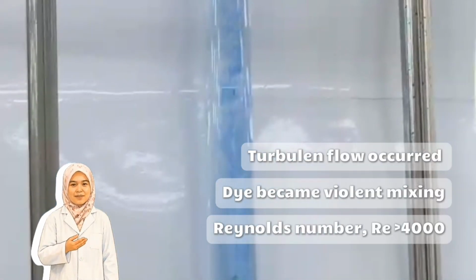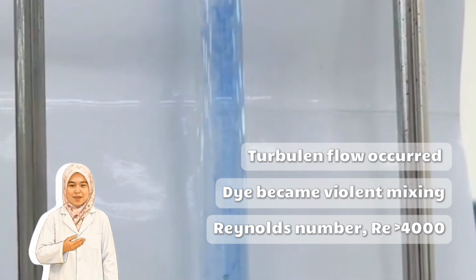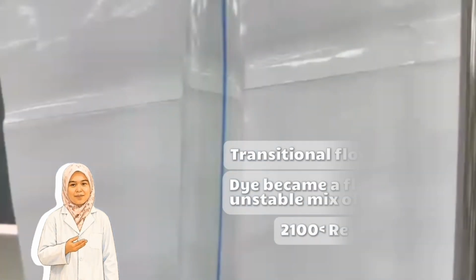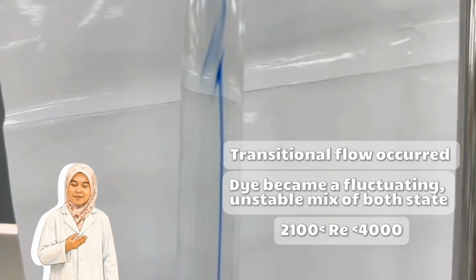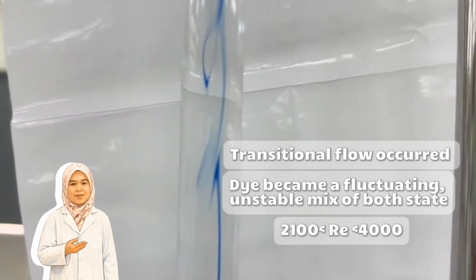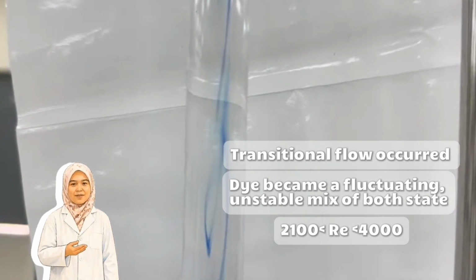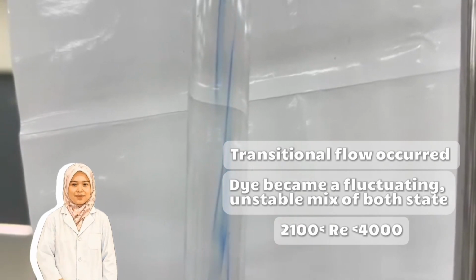And then the last part is transitional and turbulent flow, where the valve was readjusted to increase the water velocity until the dye began to mix or become unstable. Transitional flow was observed when the dye started to fluctuate, occurring at a Reynolds number between 2100 and 4000. Turbulent flow was reached when the dye dispersed and mixed completely with the water, occurring at a Reynolds number above 4000.